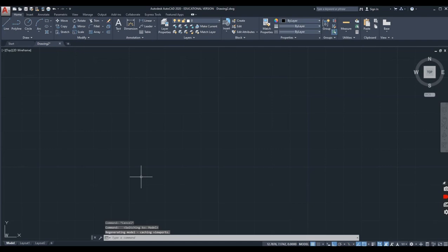So I'm going to go here to model space, and I'm going to start drawing that little support base. I'm going to start here, and I'm going to draw a circle, and let's see, I want the center and diameter. And I'm just going to pick a spot, really doesn't matter. I'm going to pick the big diameter, and that's 2.